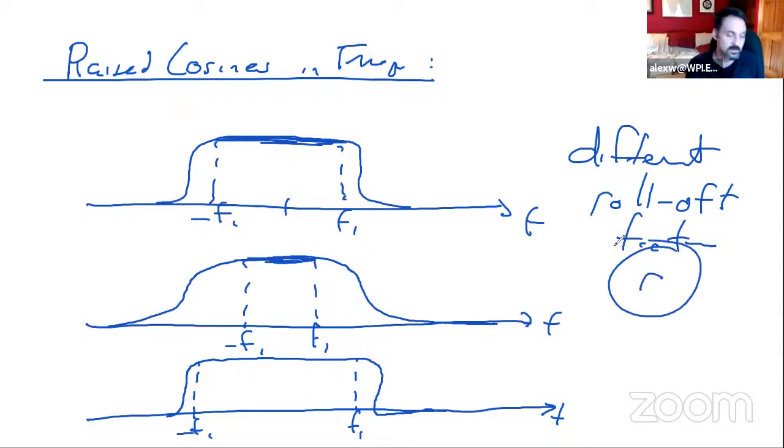And this really depends on the application that you're using these raised cosine functions for. One thing you want to be mindful of is that when you're transmitting information, their absolute bandwidth matters, potentially if you have adjacent communications. How do you want these to spill over or not, right?